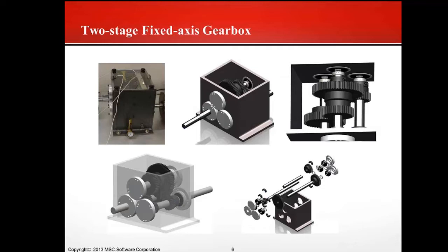Here is the gearbox, and if you look here, we have the accelerometers installed on the top of a bearing. There are two bearings there, so it's on the top. We carefully chose the location of the accelerometers in order to capture the strongest signal. We tried accelerometers in many places, including immediately above the bearing. We found this is the best place to measure the vibration, the dynamic response.